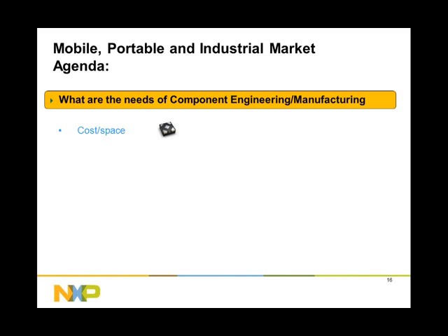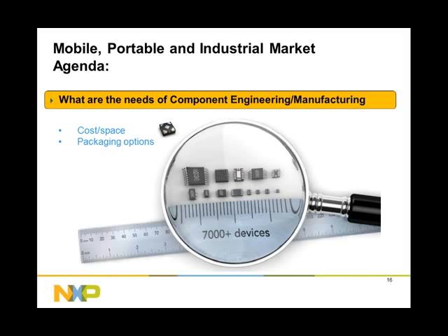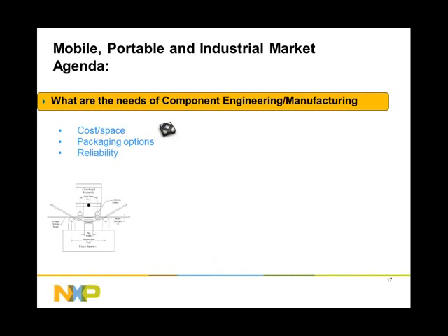And I will talk about some of the things that we have done to reduce the cost of implementation by eliminating the need for a step-down mask in the printing process on the PCB. Also, component engineers need a wide selection of package options because maybe they don't need the smallest package, but yet they want to be able to use the most effective package for their application.